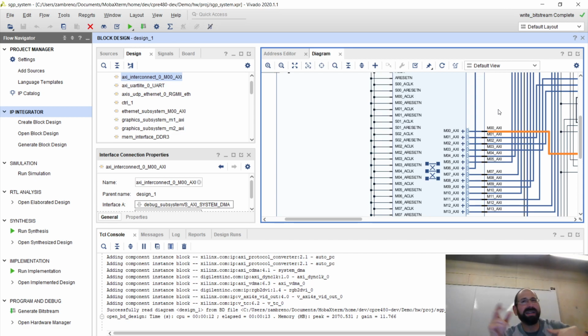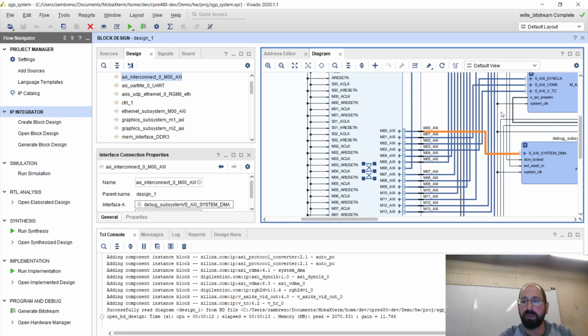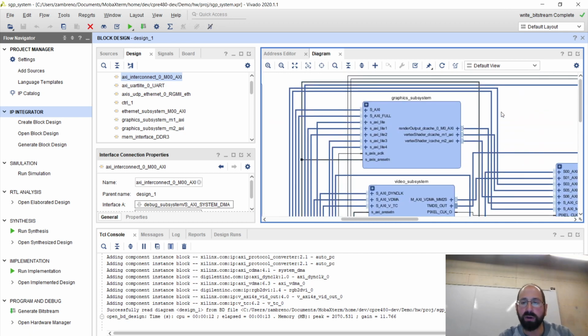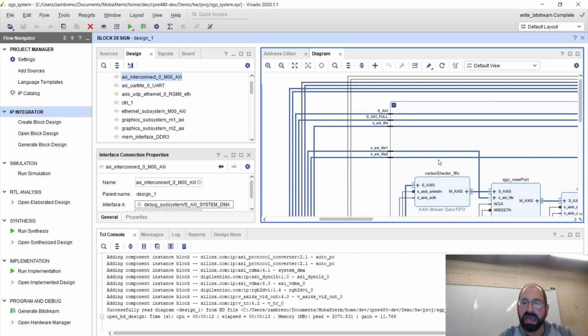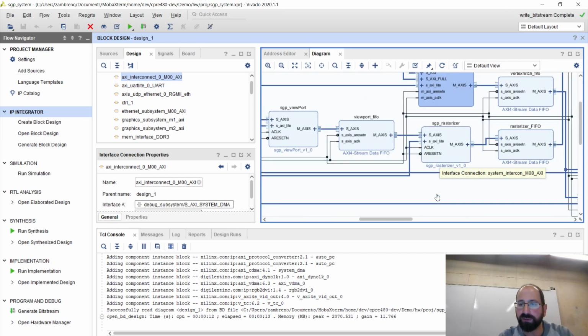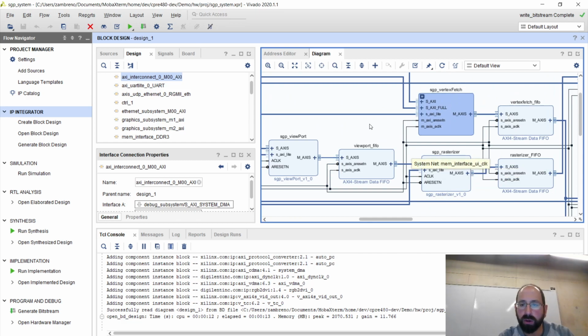So somewhere in the application, in our case it's in the driver, we do have to be aware that if this is going to a configuration register that's actually connected via an AXI Lite interface, we should only be sending one thing at a time. We shouldn't try to send 32 things or 256 things at a time. Because it does often happen that when we're dealing with our IP cores that we want to do multiple things, and this is showing more than what you have currently in MP1. This is just the version of it I just opened up. You are working on,